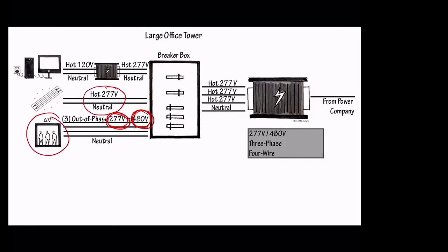And so that just depends on whether or not the building is made for 120 or 277. So if it's a big building, maybe 10,000 square feet or bigger, it may be 277. Now there's no fixed line between a small building and a big building, but if it's obviously a giant building, it's almost certainly going to have 277, 480. And if it's obviously a small building, it's almost certainly going to have 120, 208.